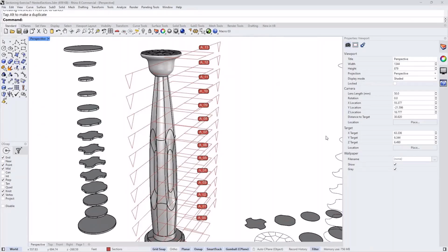Yeah, so you can think of extracting a clipping section in place. This is in its natural 3D place. It's there, and it basically intersects the clipping plane with the objects or the model and creates it there in the 3D space. If you want to extract it as a drawing, with backgrounds, maybe to put in layouts, or that is flat on the XY plane, then you run the clipping drawings command in that case. So this is the main distinction between the two.